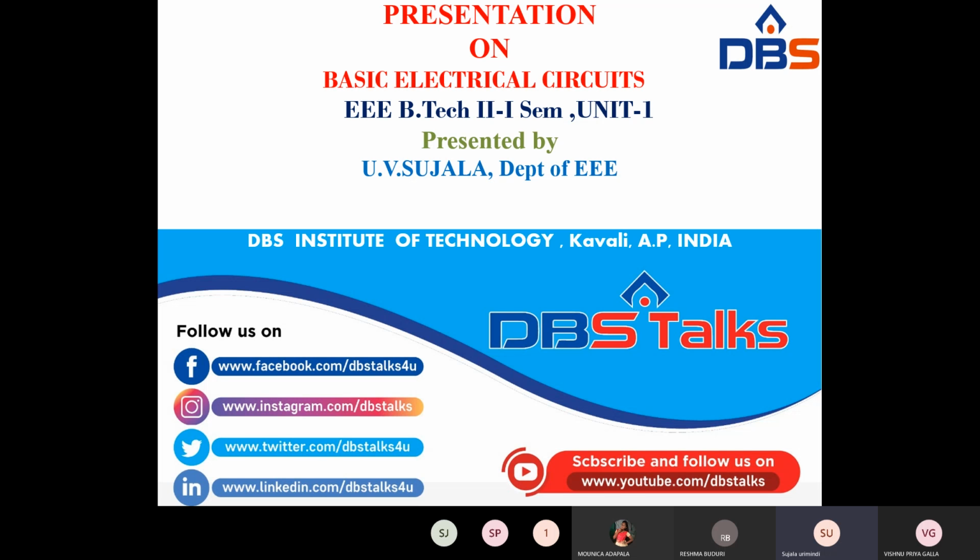If suppose the direction is opposite, then whatever minus signs were there will become plus, and the remaining plus signs will become minus. Depending upon the direction, entering is put as positive and leaving is put as negative. So first we have to assume the loop, and then we have to assume the polarities. And the third thing is to write down the equation. How do you write down the equation? The algebraic sum of the voltages is equal to 0.